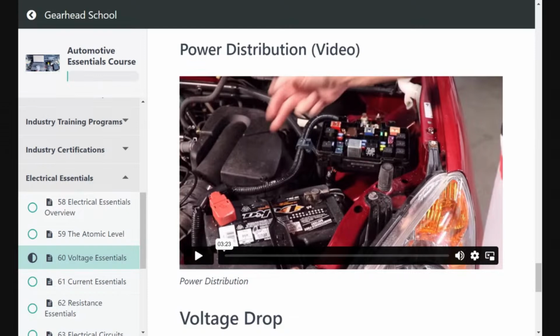I can tell the RPMs, the fuel pump, and the injector panel movement. Really high-end topics, but I can get a lot of diagnostic information from looking at the current flowing through the fuse box using a current clamp, scoping this and looking at the current change down to the milliseconds. It was a game changer when it came out 10 or 15 years ago.